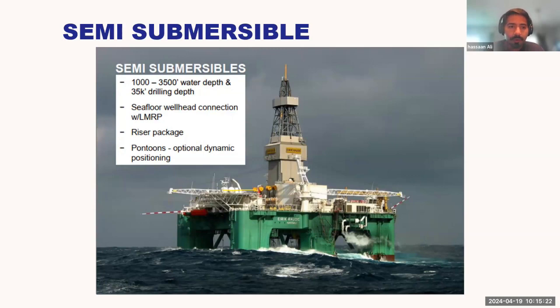They are more feasible for seafloor wellhead connections. That means you will have a subsea structure, and there's a possibility that your BOP will be lying there on the seabed. They are more feasible for 1,000 to 3,500 feet of water depth, and they can drill all the way to 35,000 feet of drilling depth.